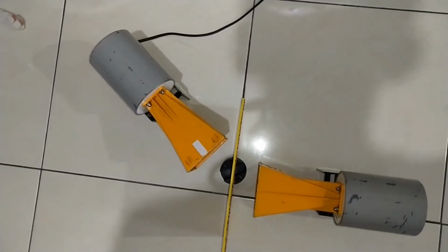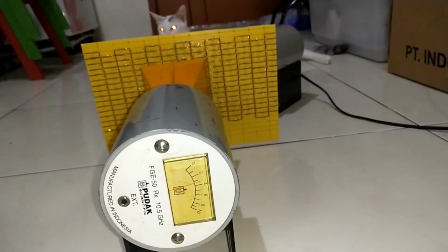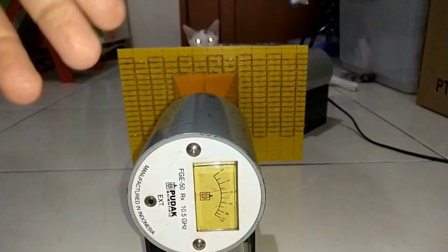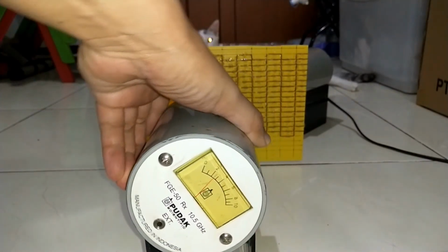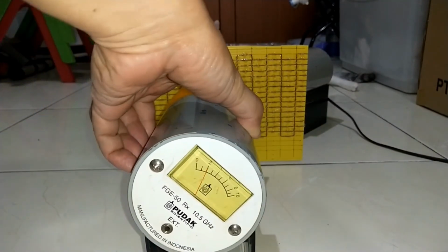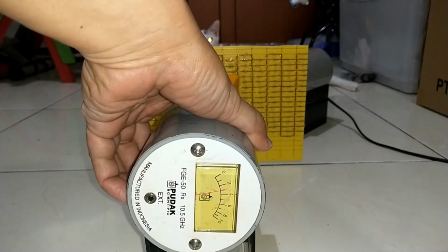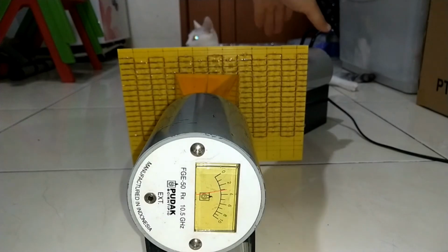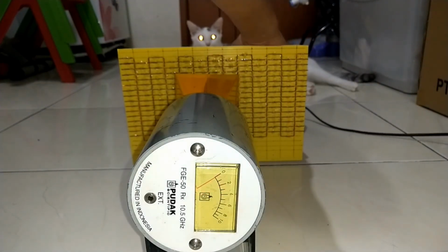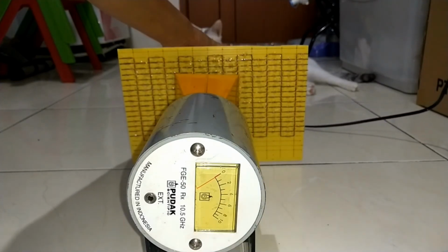Now it's time to test the polarization twister. The transmitter is polarized vertically while the receiver is polarized horizontally. The receiver is facing right to the polarization twister, but the transmitter sends microwave from an angle, around 45 degrees. We can see that the twister generates adequately high intensity of horizontally polarized microwave to be read by the receiver. When the transmitter is relocated to face straight to the twister, the receiver doesn't get the horizontally polarized signal.